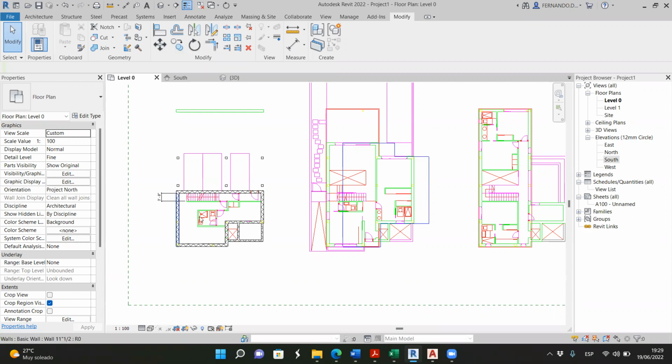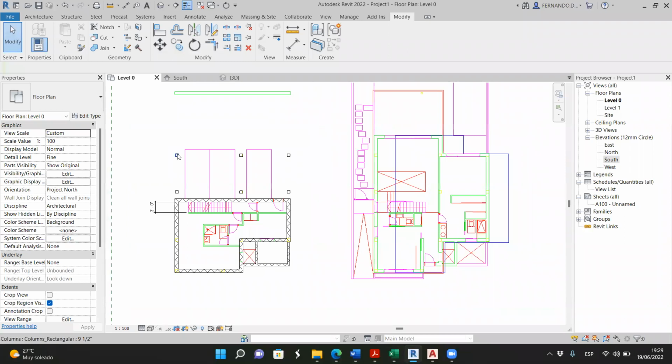Now, this is our file. So we have taken this AutoCAD file, but now the Revit file is the one that matters. We do know that all the walls have to be lined up and all the structural elements have to be lined up. Sometimes there are inaccuracies between the basement and the first floor in the AutoCAD file. And if we keep tracing things, yeah, we trace the original file, but what if the original file is wrong? Then we are making the same mistake.